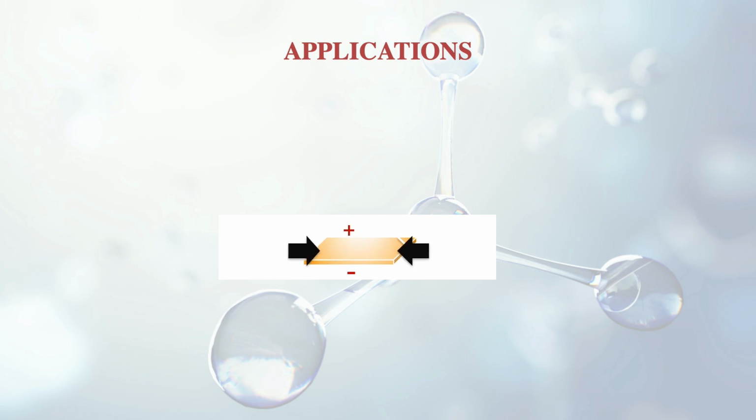Energy harvesting means that the piezo element can serve as a generator. In fact, it's a very compact generator with no moving parts, and it can produce electricity in this fashion if it is under dynamic stresses. Now, as far as the converse effect is concerned, piezo elements are used in mobile phones, the speaker, which converts electrical pulses to sound waves. They are used in fuel injectors, musical cards, inkjet printers, vibration control, turbo machinery, numerous kinds of actuators, and precision positioning.